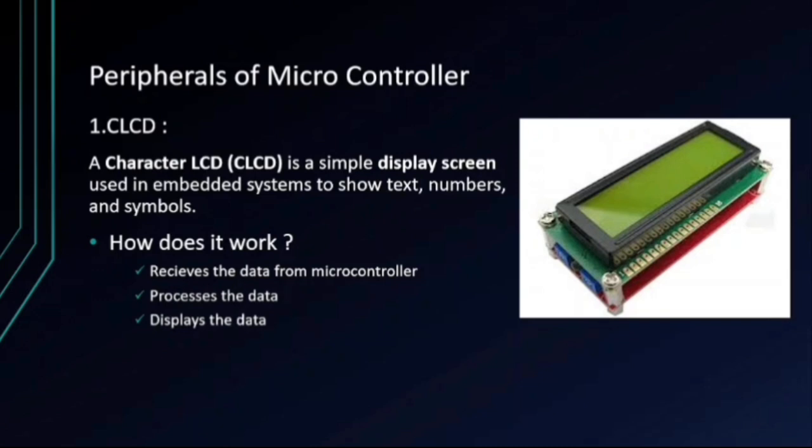When electric current is applied to liquid crystal molecules, they untwist, resulting in a change in the angle of light. The polarized layers are responsible for either blocking light or allowing it to pass through. A reflecting mirror is arranged at the back of the unit. It consists of 16 pins, and 16 characters can be arranged in a row, and there are two rows in the LCD.